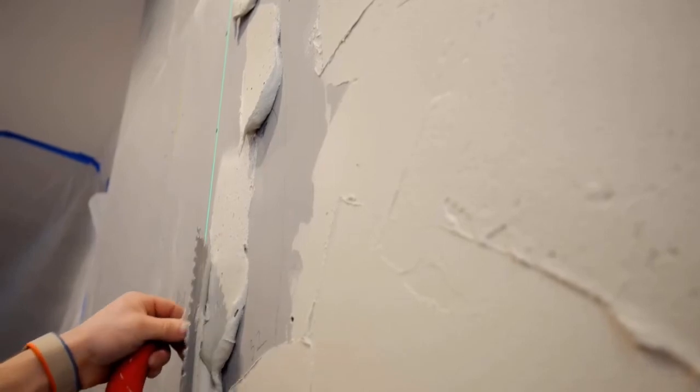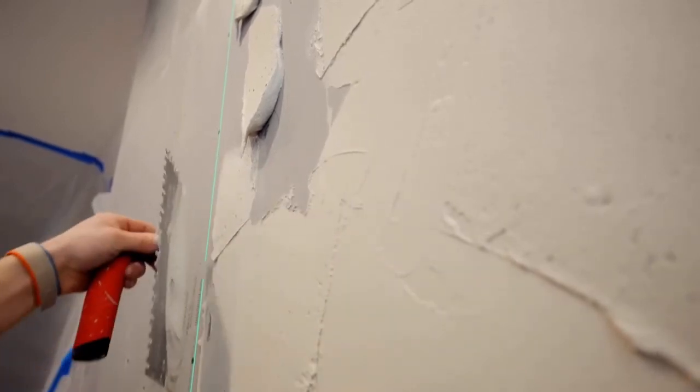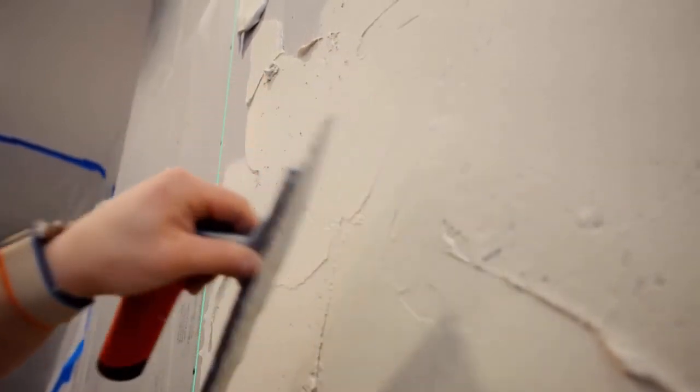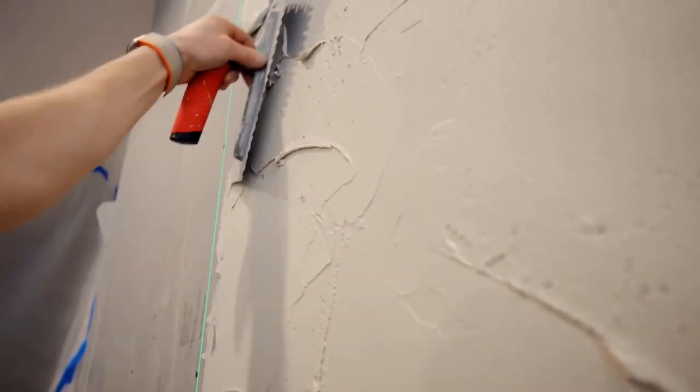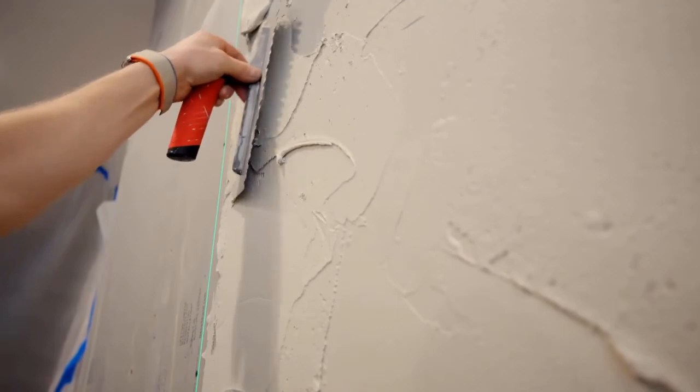So why is it required? Because it acts as a base coat, it absorbs the imperfections on the walls and makes a smooth finish. So the importance of wall putty is that it fills surface imperfections like pinholes and cracks, then provides a smooth base for paint and increases paint life and finish quality.